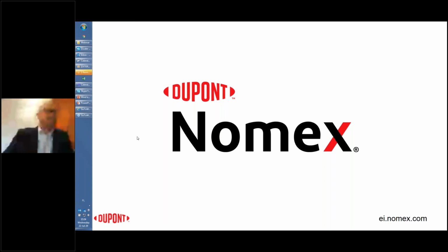Next question. What is the insulation level of transformers in offshore? As I said, traditionally it was 33 kilovolt class. Now it's moving to 66 kilovolt class. So depending on the standards, whether this is IEC or IEEE or any other regional standards, the insulation level would be selected based on this. But 66 kilovolt as a rated voltage becomes the standard for the offshore, with further considerations for 130 kilovolt class.